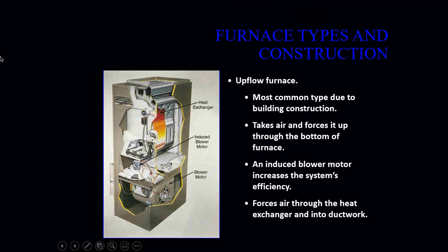It takes air from the bottom and draws it up through the heat exchanger and then back out. It uses an induced blower motor, which increases the furnace system efficiency, and it forces air through the heat exchanger into your ductwork.